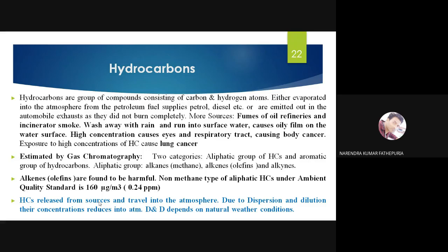So how much CO2 can be accepted, how much hydrocarbons can be accepted in the particular atmosphere, and how will you decide the green zone, red zone, yellow zones, severe zones, and sensitive zones, right, based on the air pollution, or what is the percentage of air pollution that we are getting in a particular area. Suppose the assessment of particulate matter is getting very high, more than 300 to 400 micrograms per cubic meter, it means this area is called very sensitive. I will be talking later about the zones and all the air quality monitoring standards, right?